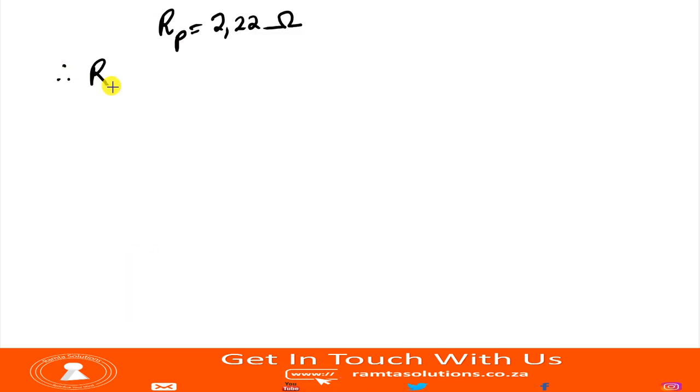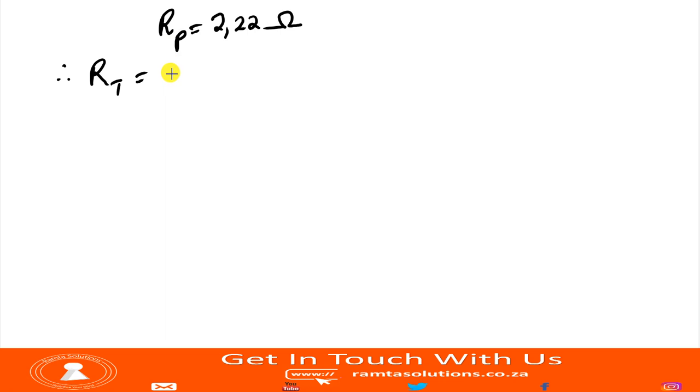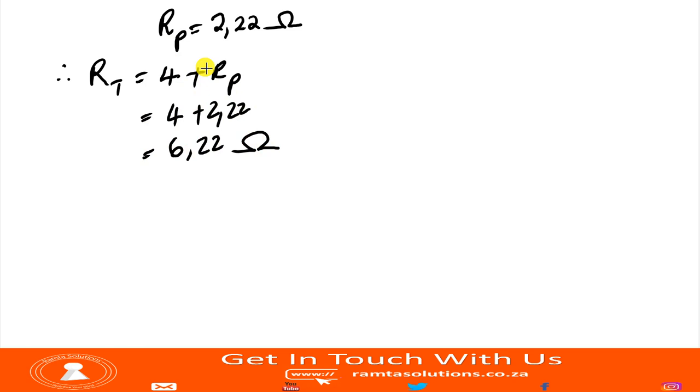Now, the question wanted us to find the total resistance. Therefore, total resistance is this resistor here plus the R sub P, because when you say R sub P, you're now connecting them in series. So it's 4 ohms plus R sub P, which is 4 plus 2.22, and this is 6.22 ohms. This is your total resistance.